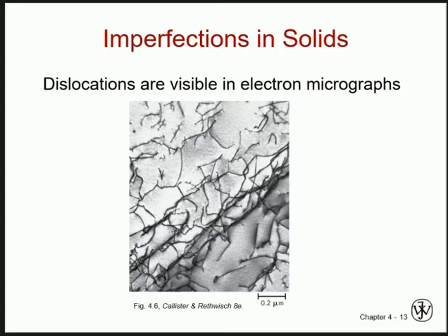So in the last lecture we discussed dislocations, why they are formed within the material, and why they are critical to the deformation systems. So the thing is, whenever a material deforms, it is going to deform when the atoms move from one place to the other. This is how the material deforms. So atoms do not move randomly in any direction when the force is applied.